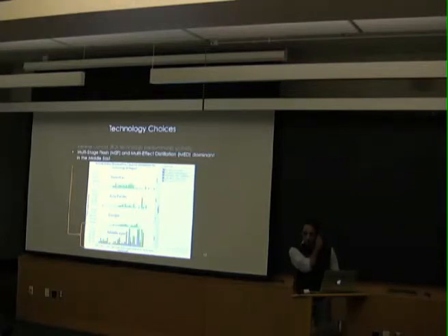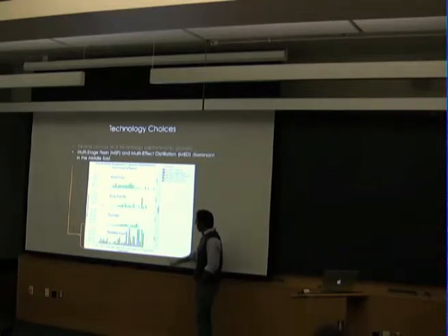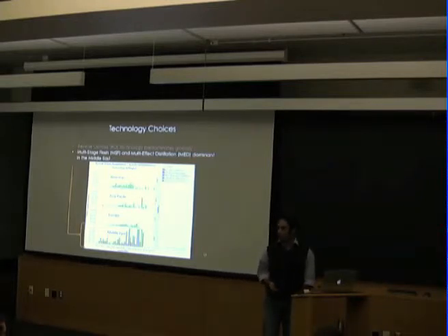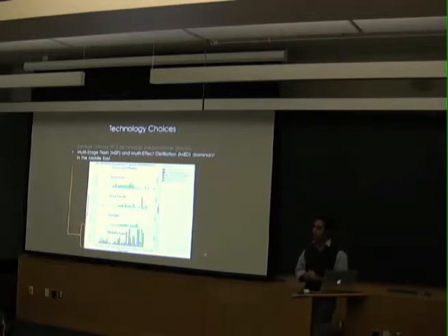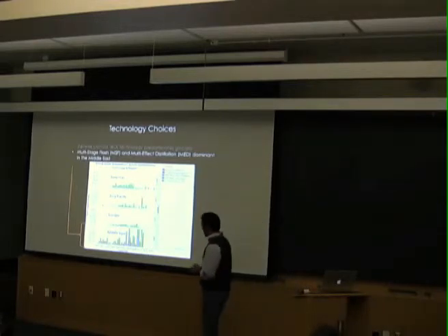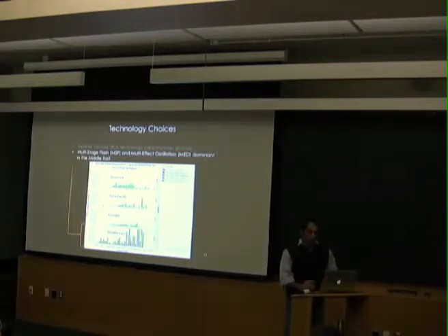But if you unpack that picture a little bit more, you'll see that most of those happen to be in the Middle East. So flash and distillation, these are thermal processes, whereas reverse osmosis is a mechanical process. And depending on what energy inputs you consider, particularly oil, heavy fuel oil, and gas, which tend to be available locally in the Middle East and at very subsidized prices, that might be one of the factors that drives the selection of that particular technology in that part of the world. But actually, there's a fair number of reverse osmosis installations even in the Middle East, so that doesn't really explain the whole picture.